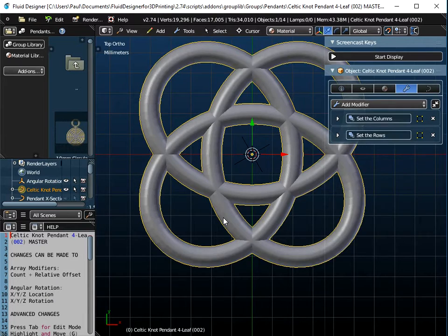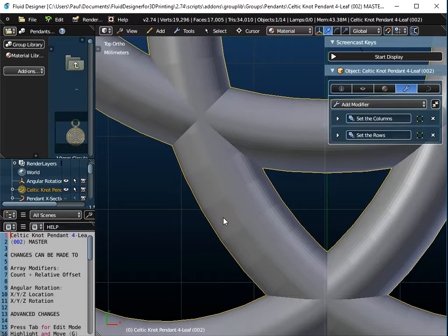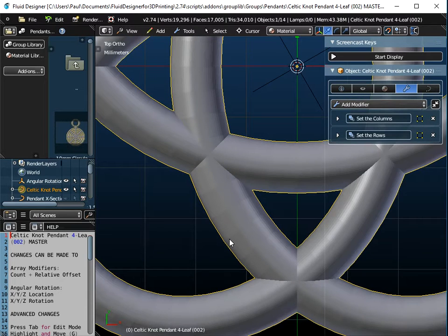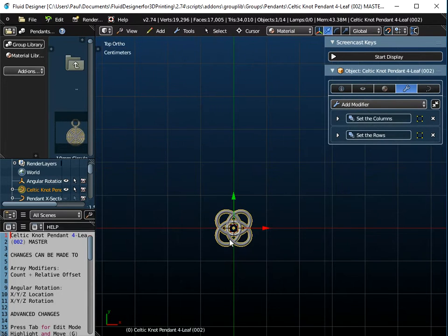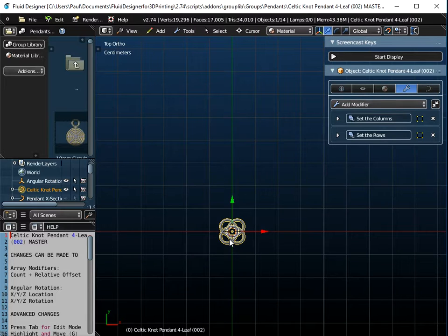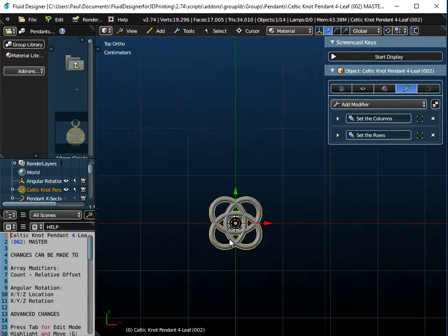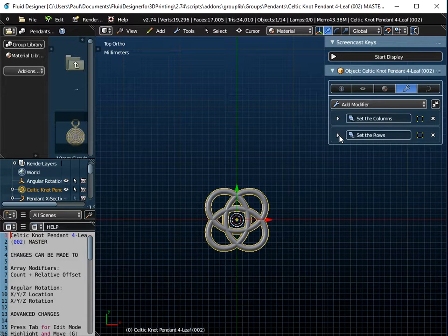So you do have to consider, as I said in the previous video, whether or not to keep this kind of chunkiness here or to smooth it off by changing this to a NURBS curve. In this instance, I'm going to keep that. Now, you've got to remember that the real size of this is really going to be like that when it's 3D printed, so you're probably not going to see the problem. Alright, so what are we going to talk about here?